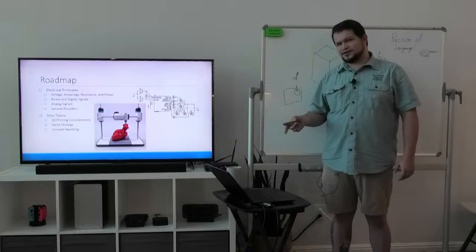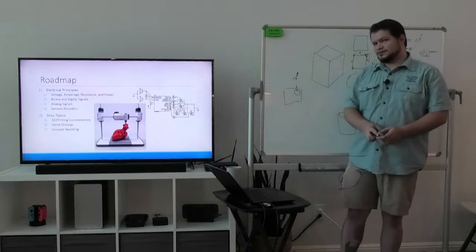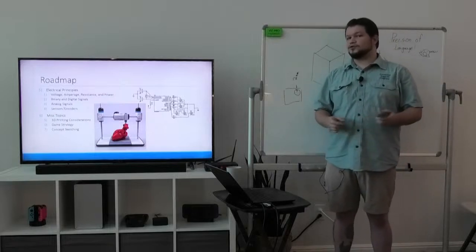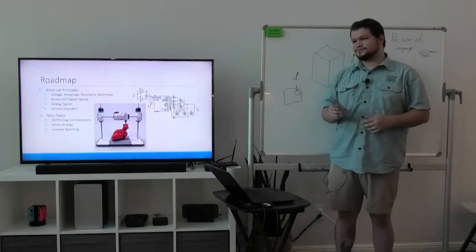I have a hand raised. Go ahead. Can you CNC countersunk holes? Yes, you don't have to CNC them. If you're laser cutting them, you cannot. The laser will not do the angles unless you have a very fancy laser.